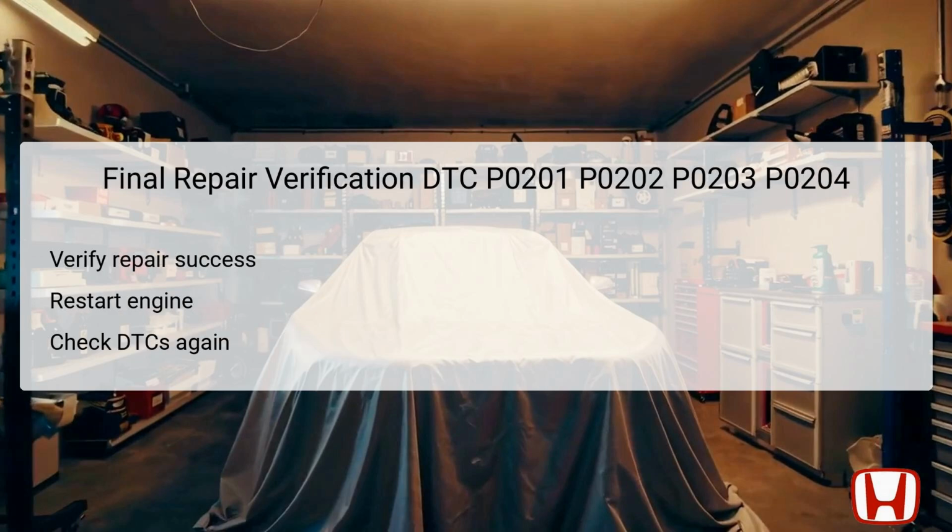After completing repairs based on the previous troubleshooting steps, verifying that the system is functioning correctly is essential. Begin with restarting the engine and allowing it to idle for a few moments. Once you've done this, use the HDS to check for any remaining DTCs. If no DTCs reappear, it confirms that the repairs were successful and the injector circuit is now functioning correctly.